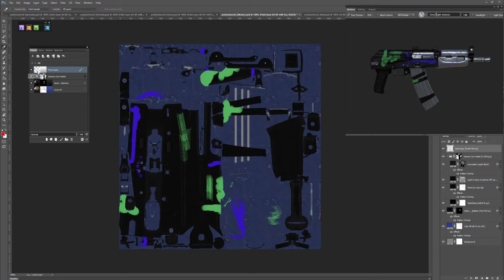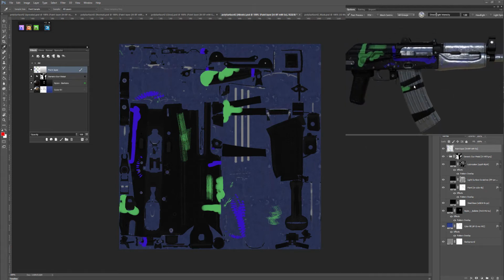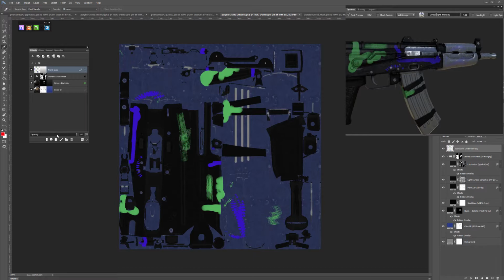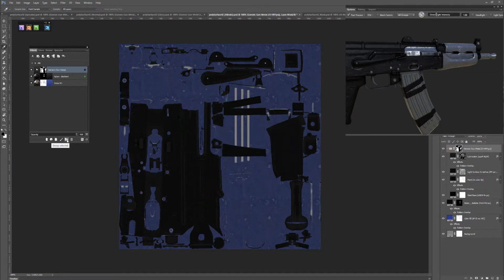If I wanted to, I could still have a mask on this. I could still apply a color ID, or I can just toggle back on and go into paint mode some more. It's all up to me, but I have some nice ability to actually paint on my model, which is extremely nice. And of course I have my opacity slider here, so if I wanted that lower, or if I just want to set this to screen. I'm actually going to hit the delete button on this layer because I don't need this.